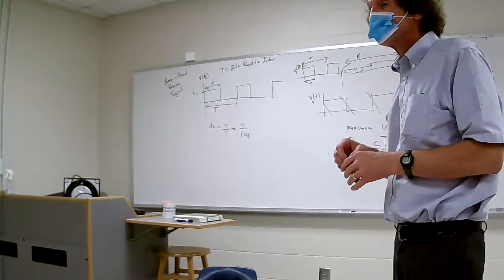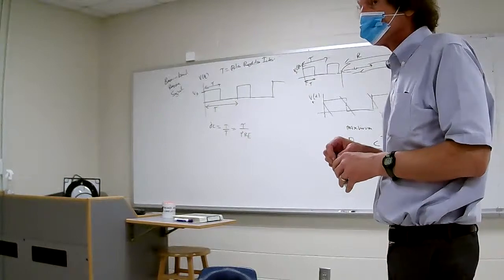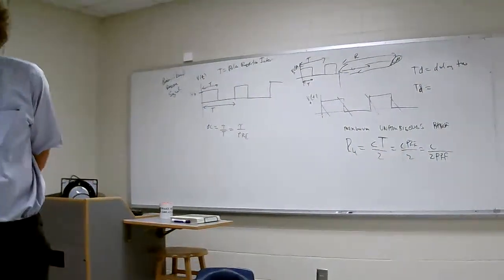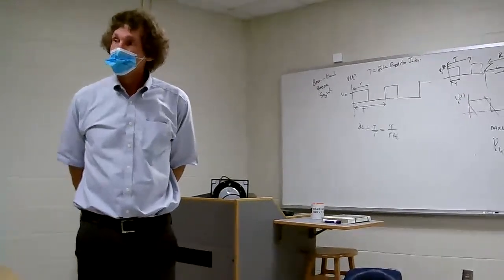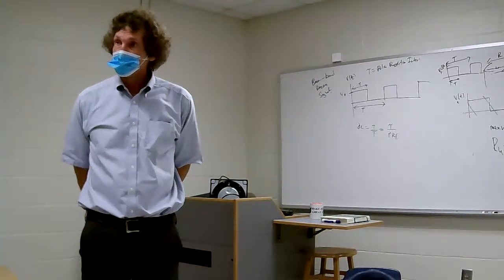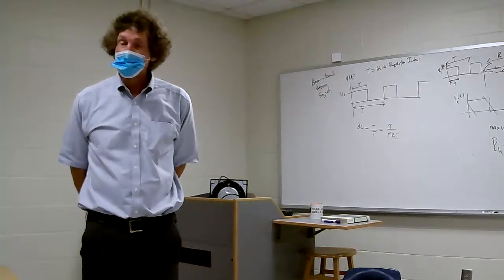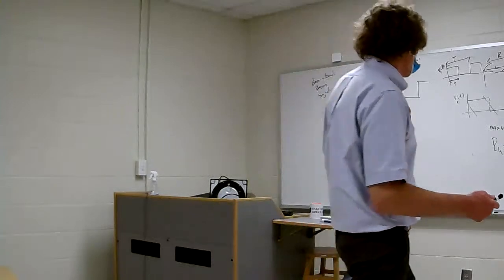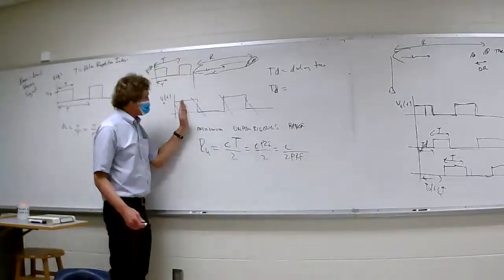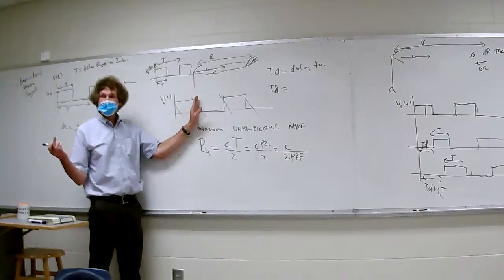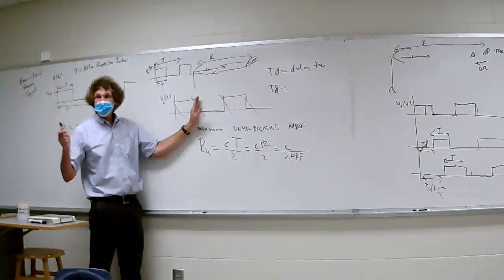When you're receiving the power from the antenna, from the object that you detect, how are you separating that signal returning, because you have the transmitter going to your antenna? This is a wonderful question. Remember one thing I said: when I'm transmitting, anything I receive back up to this point, I won't be able to see. It's called eclipsing. This is a very important point.